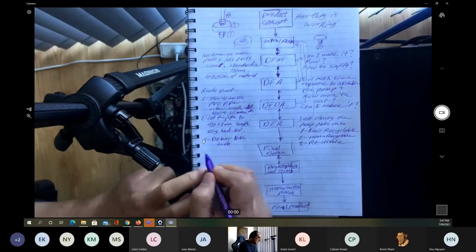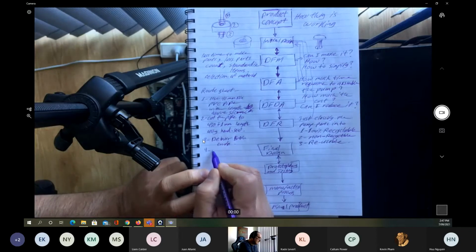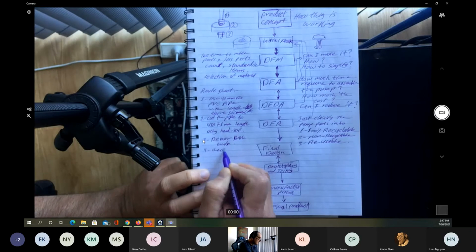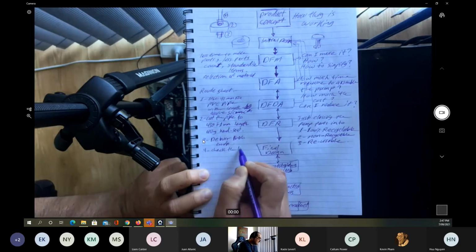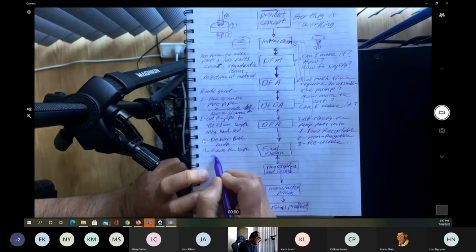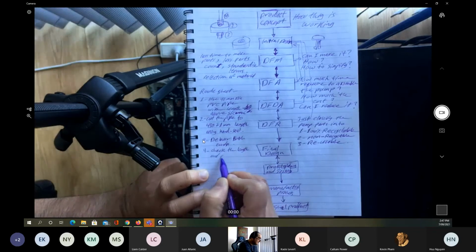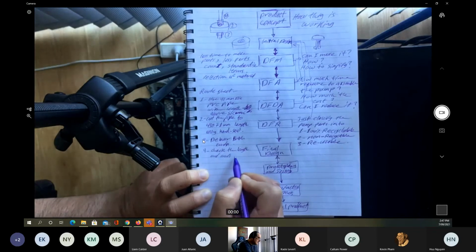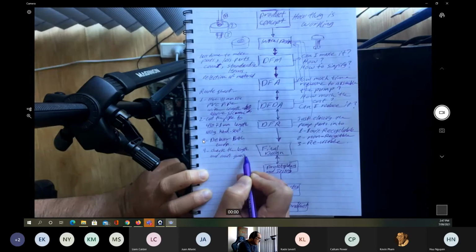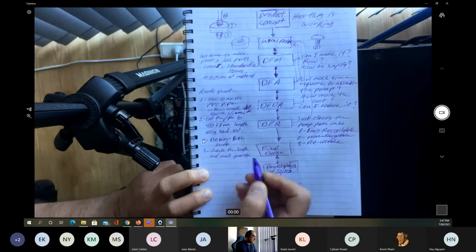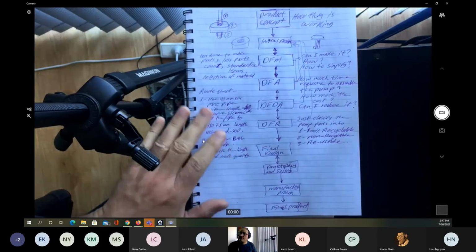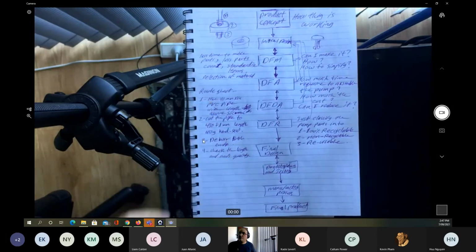We can simply say step number 4 is check the length. This will be the inspection process. Just check the length and end quality, just to check if they have any burrs or not, just push it aside. Now done. That's an example of the route sheet.